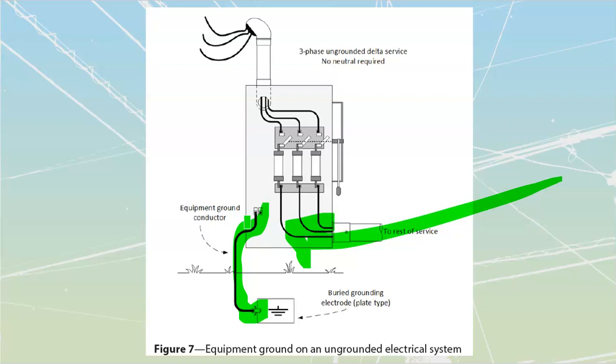However, it doesn't do anything to operate the system. These types of systems, an ungrounded system like this, are going to need additional monitoring components. You'll learn about those inside of third year. Particularly, we are going to have alarm relays and these fault lights that are going to be continuously watching what's going on inside of it.